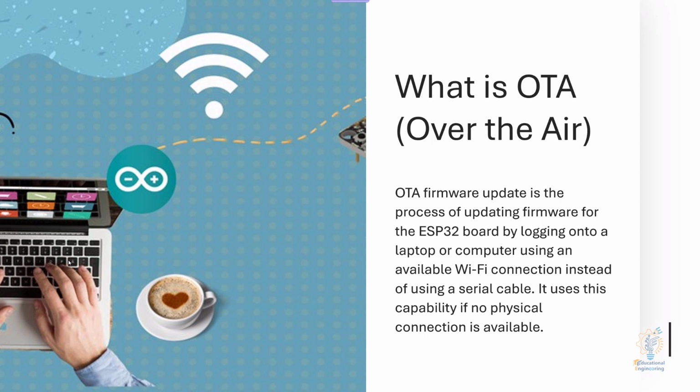Plus, if you are sharing a device or a product and you want to keep sending updates to your customers, this is the feature to look for. OTA update helps you update your code wirelessly over the internet or over a local network connection without a physical cable, without the serial USB cable that you usually use to upload your code to your ESP boards. This feature allows you to enable updates over the air. That's why it's called OTA update.